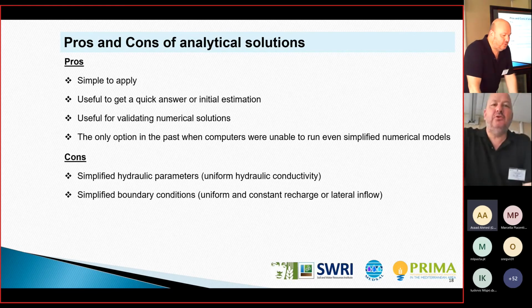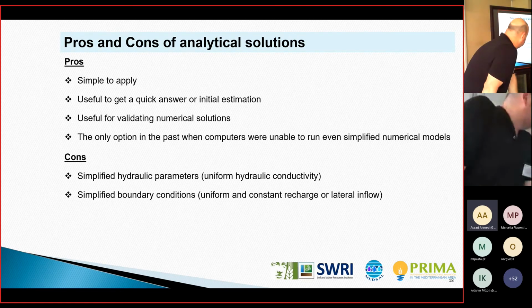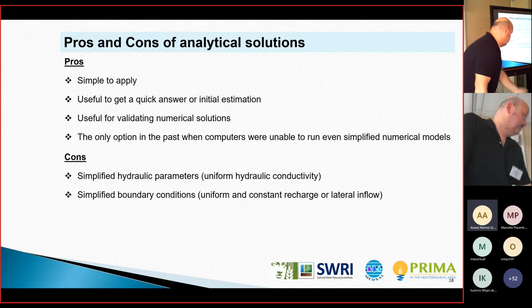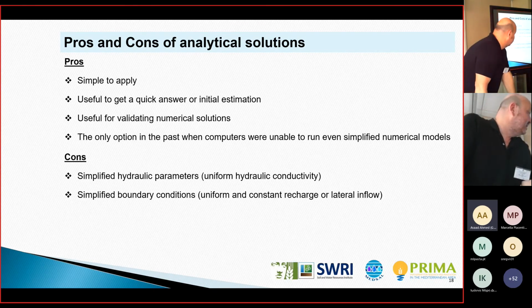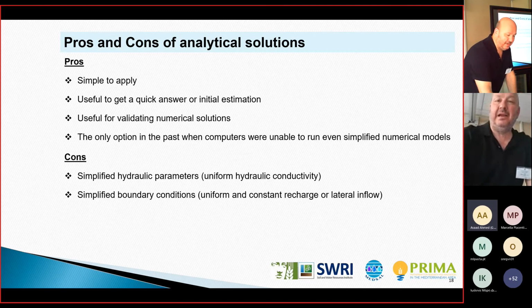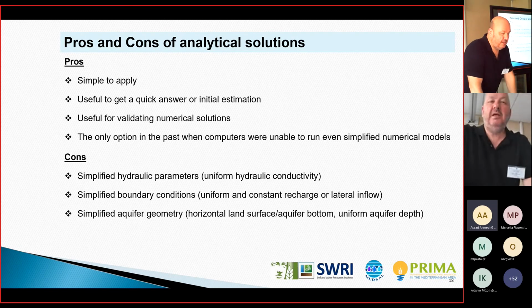Some disadvantages or limitations, if you prefer, are that analytical solutions usually adopt simplified hydraulic parameters, uniform hydraulic conductivity, for example, simple boundary conditions, spatially uniform and temporally constant recharge or lateral inflow, and simplified aquifer geometry.